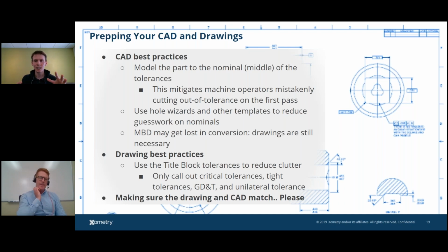But just understand that when it comes to that digital thread of here's your part, here's an upload to our site, and here it goes to our manufacturer, our manufacturers may be reading a STEP file or some other file type that is not the native, because they may be used to putting it up to their CAM program. So if all your work is in model-based definition, we still really would like that drawing for reference on anything that is threaded, tapped holes, tight tolerances, or other critical features that are not general standard to that process. In the future, I hope 5 years from now, everything's model-based and my life is beautiful.